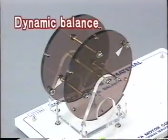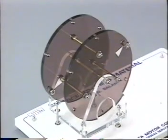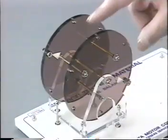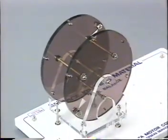Now let's see the dynamic balance. The tire has thickness. So let's suppose that heavy spots are located inside and outside the disc assembly. In this case, the disc assembly can stand still at any position. In other words, the disc assembly is statically balanced.